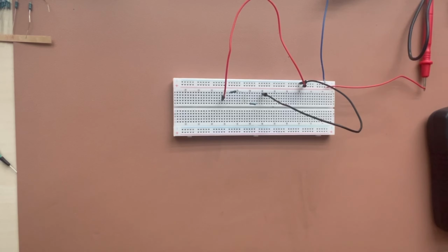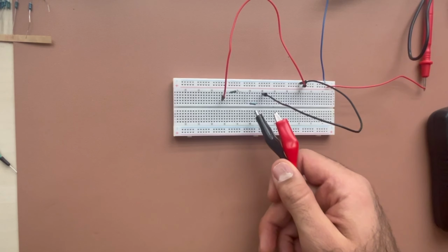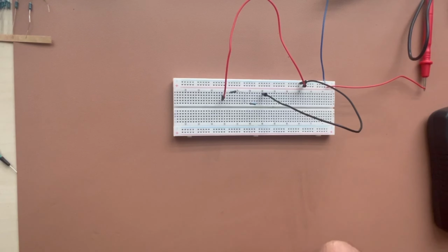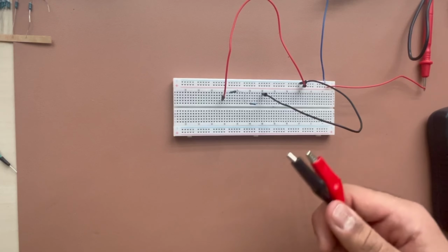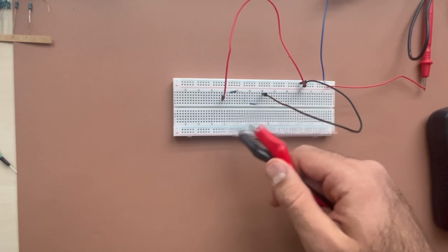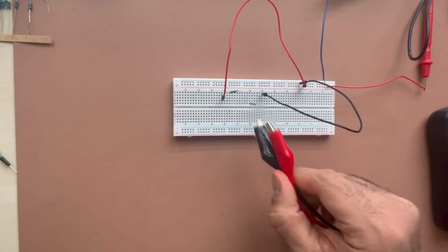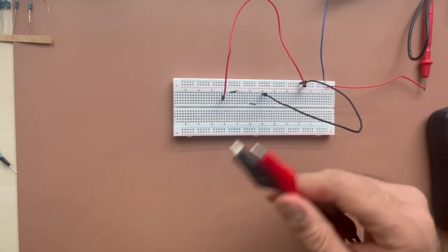we did, we found out in order to get 2 volts out of the second resistor, which would be this guy, we need 330 ohm, and we need the 2K itself. So again, we are going to prove the voltage divider, whether it's working or not. So based on our assumption, if we do have this combination of 2K and 330 ohm, while we do have the voltage source of 15 volt, the voltage of this guy should be 2 volt or negative 2 volt.